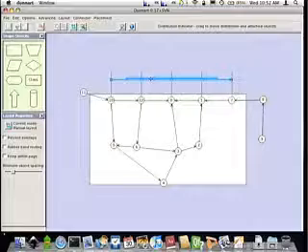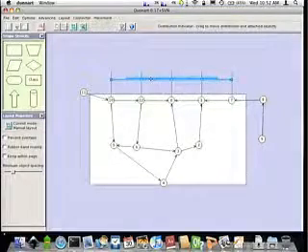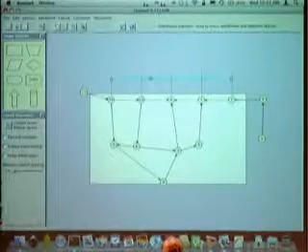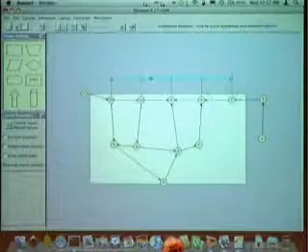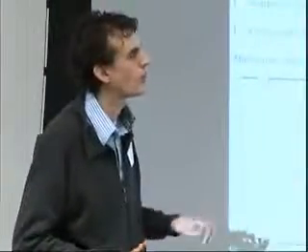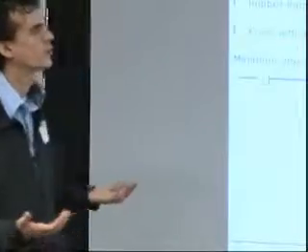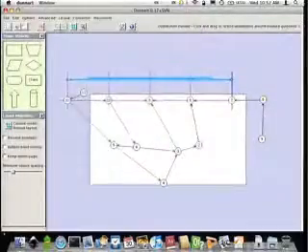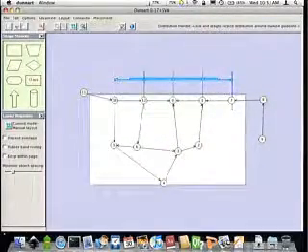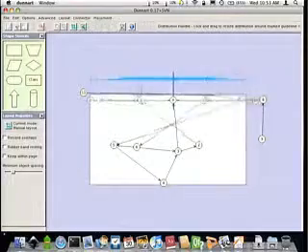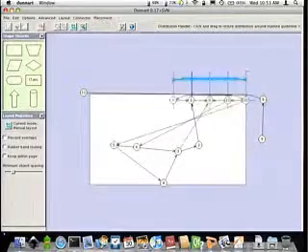We're trying to have a visual representation of all of the underlying constraints, so you can tell what's going to happen before you even interact with it. Also, this is an object that you can use to alter or remove the distribution relationship. So I can hit delete and remove the distribution relationship. The guidelines will remain. I can resize the distribution. In fact, I can choose to resize it around any particular guideline in here if I choose to.